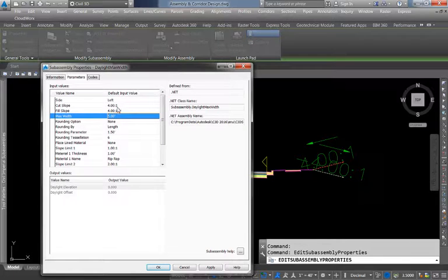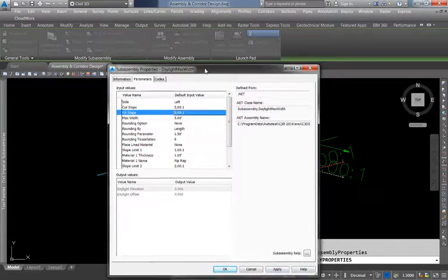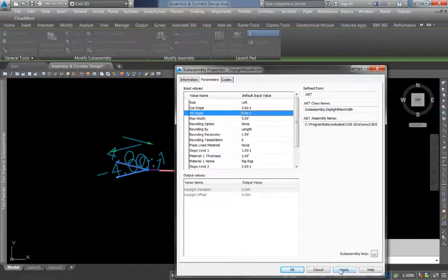And a 4 to 1 slope, that's pretty steep in some cases. Maybe I want to change that to a 5 to 1 slope. And all I have to do is type in the whole number 5, and it automatically gives me a 5 to 1 slope. So we're going to change that 4 to 1 to a 5 to 1. So watch it change when I click apply. There it goes to 5 to 1, and it has shortened up the maximum width to 5 feet.